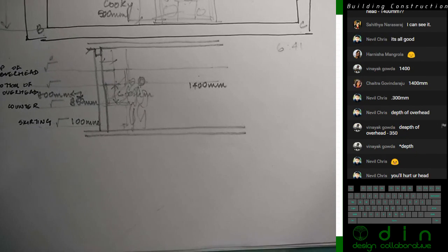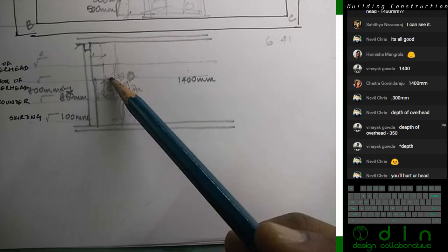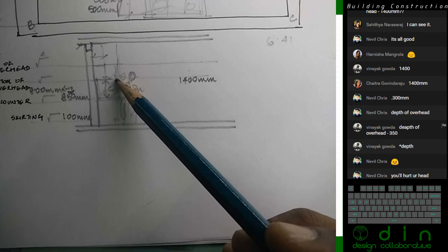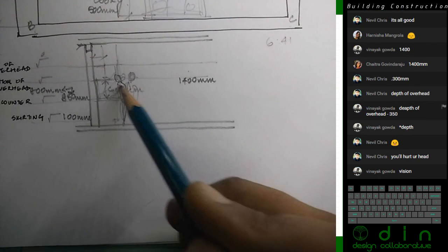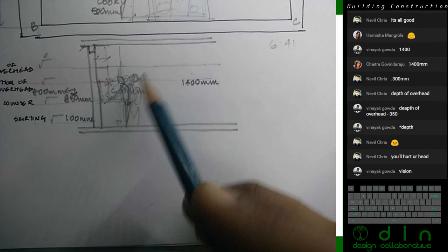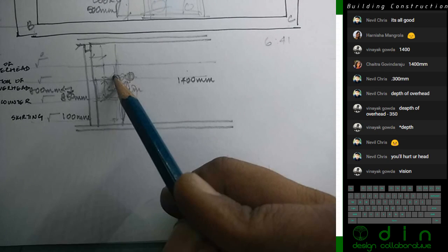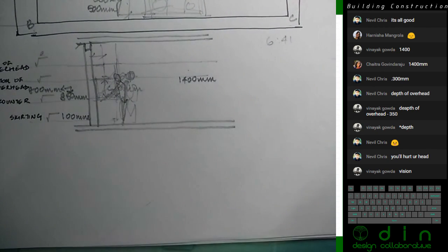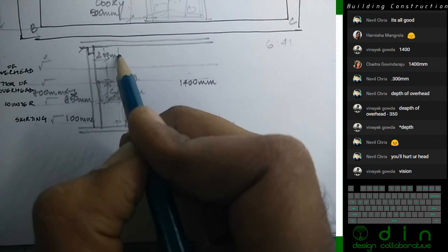You'll hurt your head. That is exactly the point. It's going to cut down on a lot of vision, but the idea is that you should be able to put your head there and do work, right? You don't stand back and touch that. You're slightly bent forward while doing this, and you can look almost straight down onto the things you're doing. So the depth of this has to be approximately 300 mm.